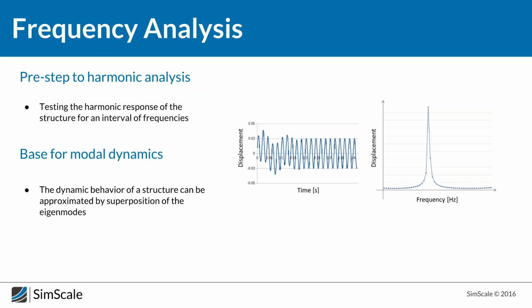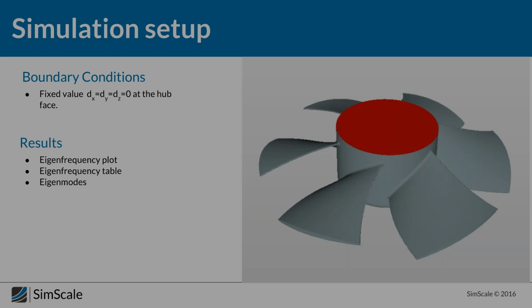Of course, we cannot calculate an infinite number of eigenmodes, but up to a certain degree you can measure how accurate it becomes. So of course it's an approximation, but from the computational cost it's really less effort. So it's very likely that you at some point want to do a first step in this direction and do a modal dynamics analysis of your structure.